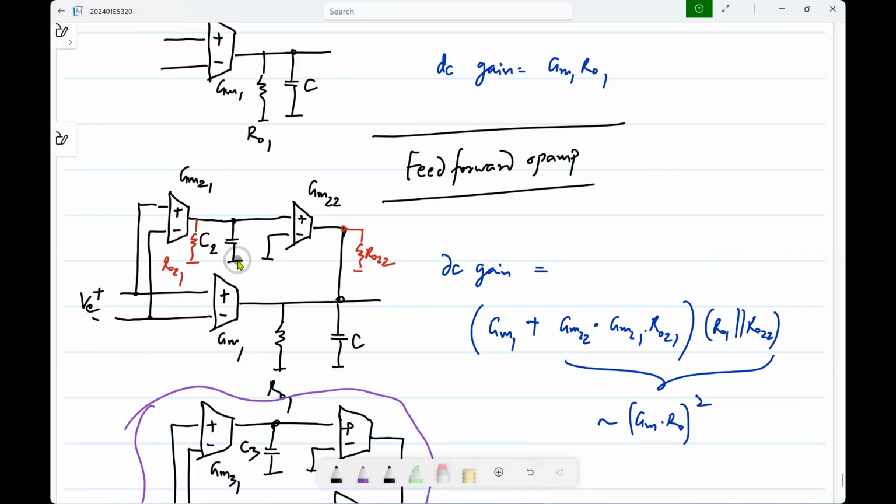Right. What was our goal, first of all? What was not good enough about the first op amp, the one on top? What was the problem? DC steady state error. Okay. And we added the second path to do what? To compensate that. Now, the way we are doing it is based on the input voltage VE, right? VE will reflect the steady state error only after steady state is reached.